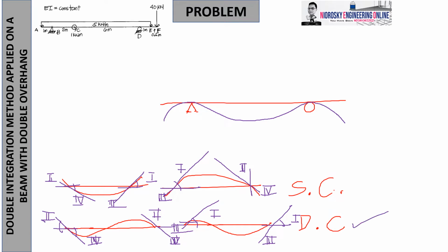Second, in a single curve, the deflection is one-sided. Meaning all of its deflection, if downward, should all be downward on the specific span. Likewise for single curve under negative bending, all the deflections should be upward. While in double curvature, there is a portion going downward and then a portion that suddenly goes upward. Likewise here, it is up and then suddenly goes down. That is the nature of a double curve in one span, so there is also a shifting of deflection.